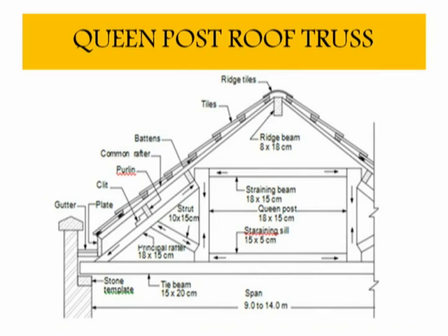Here you see the sketch of the queen post roof truss. You can see the two posts which are known as queen posts. They are connected at the bottom by the beam. The inclined members are known as struts. At the top the roofing tiles are provided, and on the topmost there is a ridge tile. So the important components are the rafters, the purlins and the tiles. This truss is supported on the wall.